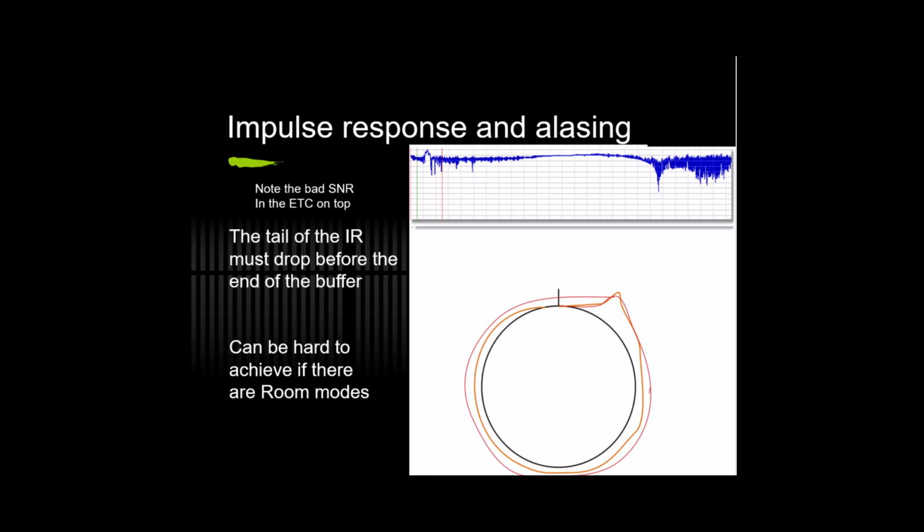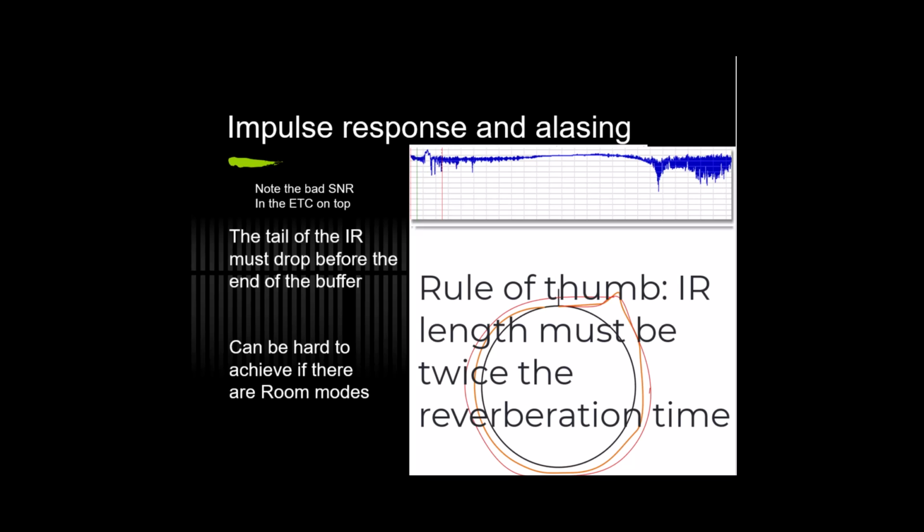I have seen this problem in many files which have been sent to me from users. Their problem has been that they have aligned their top systems to the room resonances instead of to the subs. To measure room resonances, you require a quite long impulse response, at least 4 seconds.